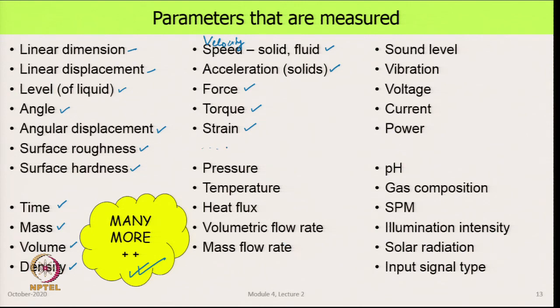Then we have another family of measurements that comes in a lot of thermofluids. The most fundamental being pressure measurement, temperature measurement. Then there is a device which measures the heat flux, what is the rate at which heat goes into a surface, volumetric flow rate, mass flow rate, and of course, here it was fluid velocity on a point wise measurement. Then we have other parameters like sound level and of course, the frequencies that are there, vibration, and then electrical measurements like voltage, current and power, and of course, many more things on the electrical side.